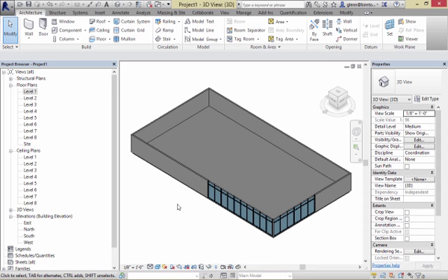We now want to go through and take that single floor and copy it up to the other floors. And I'm just going to copy the exterior walls. The truth is, if you have a lot of interior walls or some sort of core walls for the elevator or something like that, you'd probably put them in there too. I'm just going to do it with the exterior walls. The idea is to create as much detail as you want to copy to the other floors, and then just do the copy and bring it up. So I've got this basic one floor going here.